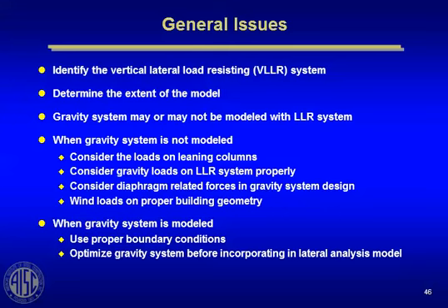So if you're only going to model the moment frame, you may have to put a dummy column in there that has all that gravity load from the rest of the floor that's tributary to that lateral load system, to be sure you properly model the P delta effect. The P delta effect can weaken a frame by 10 to 15%, so not including that gravity load in your lateral load model can cause significant errors in your drift and in potential sizing of your members.